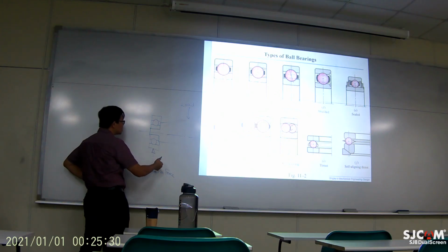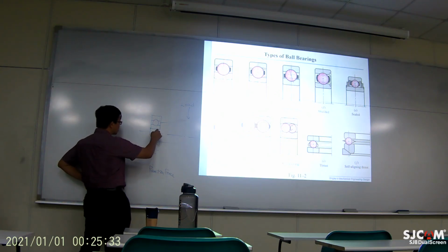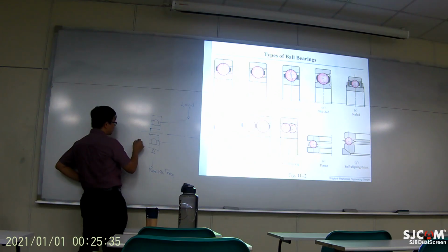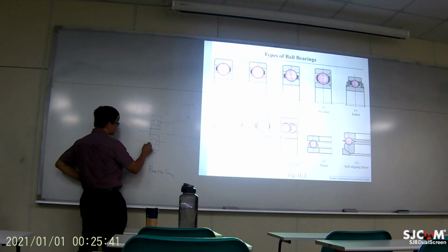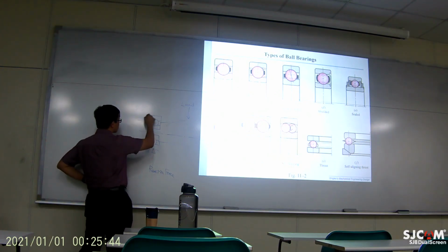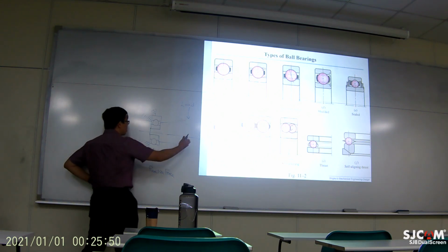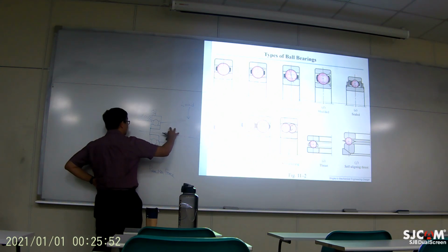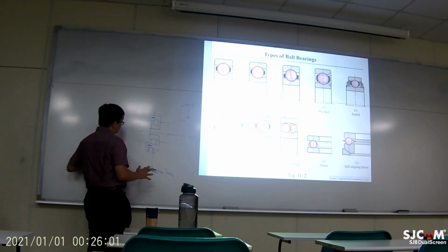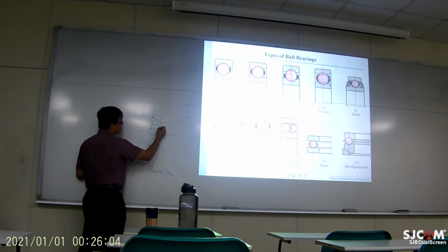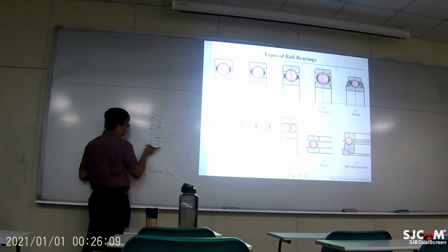But sometimes you also have reaction forces along this direction. You may have some other geometry here. So maybe there's a force pushing the shaft toward left. So there is actually some reaction force from the outer geometry pushing it back, right? So the force is pushing here from right to left, and the support is pushing left to right.